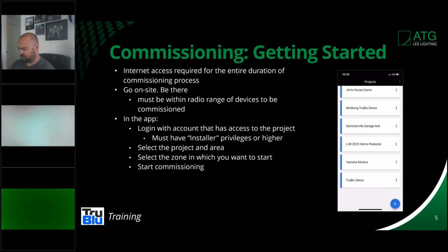Where you need to think about this is if you're like commissioning a parking lot and you have devices that might be 60 feet in the air because it's attached to an area light. There is a product that you can get that has a very strong antenna that will enable you to reach those distances. But in general, just think that you have to be within about 45 feet of a device in order to be able to commission the system.